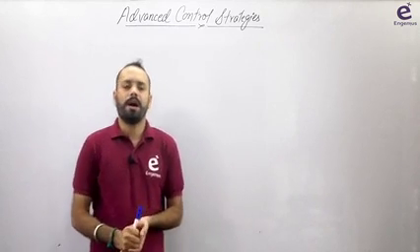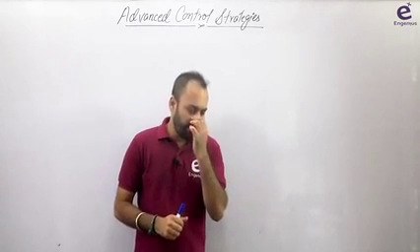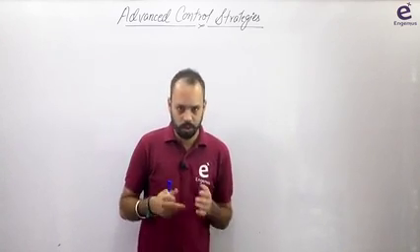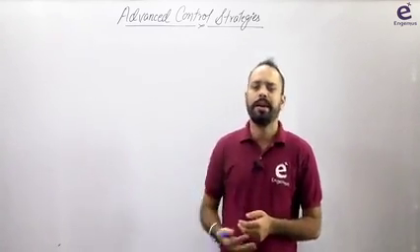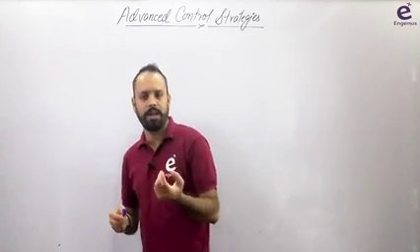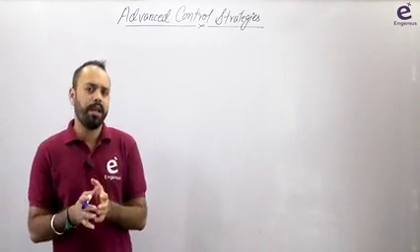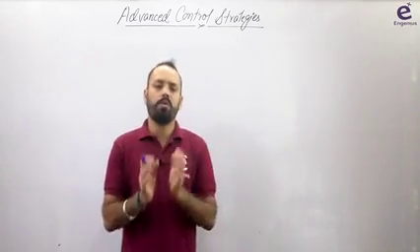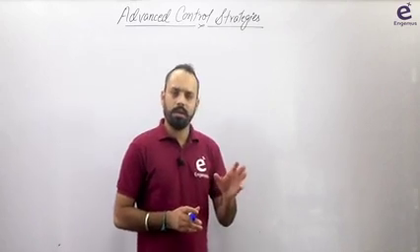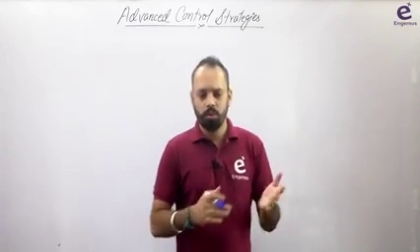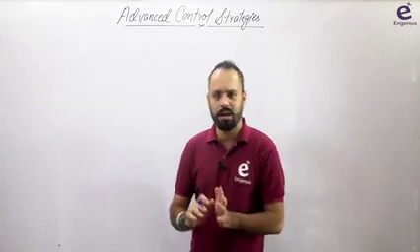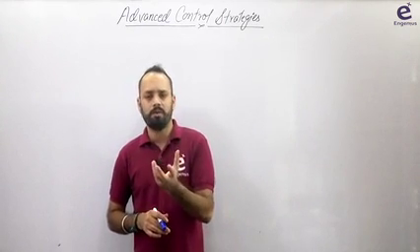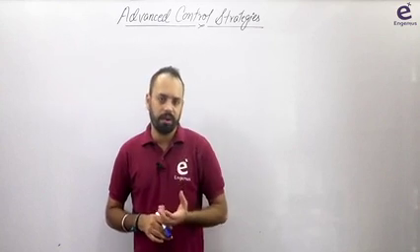That it is a kind of compensatory control, right? It means in feedback control, first a deviation from the set point is going to occur, and later a corrective action will be taken by the controller, right? तो सबसे पहले नुकसान होगा और नुकसान के बाद उसकी भरपाई होगी. And if your controller settings are proper, then the controller action will be sufficient to return back to the original steady state, and everything will be fine after that. Okay. So this is the essence of feedback control, that it is a kind of compensatory control strategy.